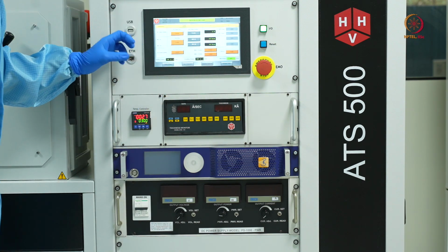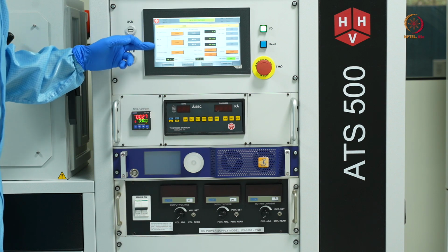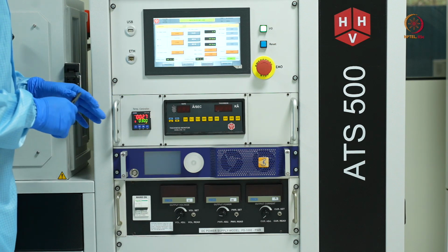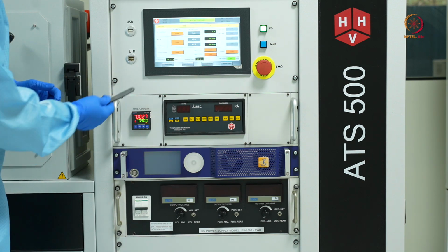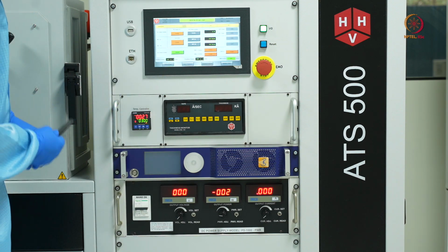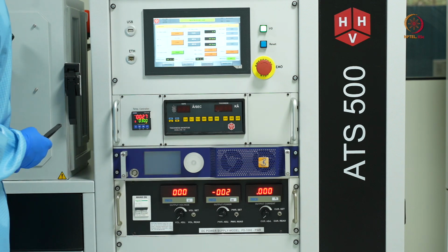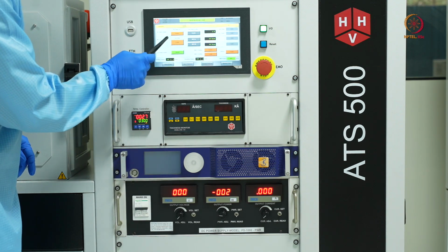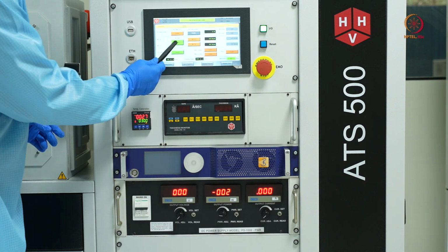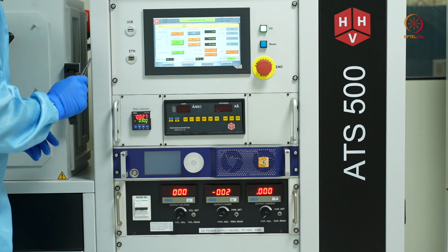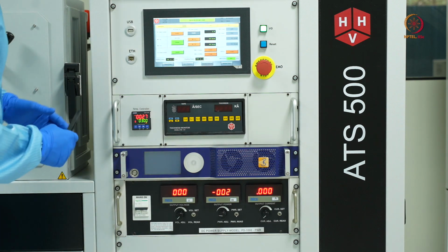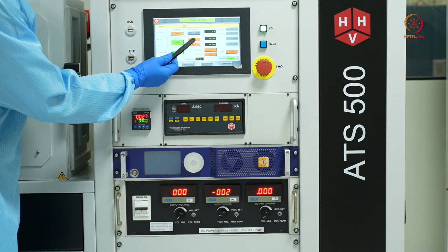and now like we said, we have certain options like RF power, DC power, and the mass flow controller, gas valves. So since we are depositing tungsten today, we'll be using DC power. So I'll just enable the DC power. You can see these panels have lit up. Next, I'll be also enabling the gas valve. Next I'll open the valve for argon gas. I'll now enable the mass flow controller for argon,